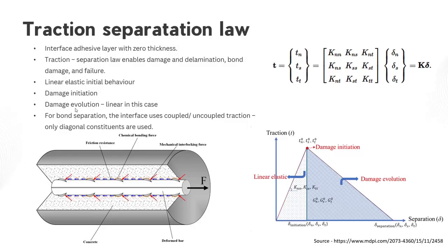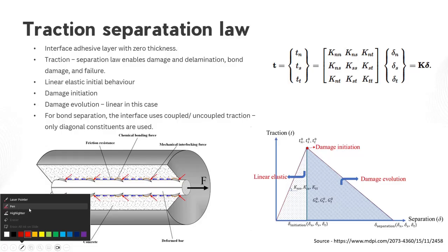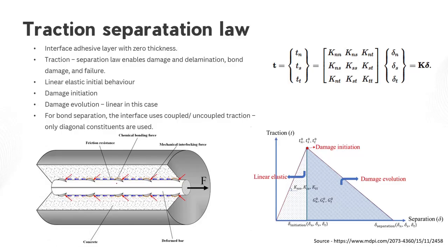Okay, traction separation law. Let's discuss what is basically behind. I will just describe what is happening inside a concrete volume. Once the specimen is subjected to axial force in the reinforcement rebars, the load transfer is facilitated by the ribs, where you can experience some mechanical interlocking, also friction and chemical bonding in between